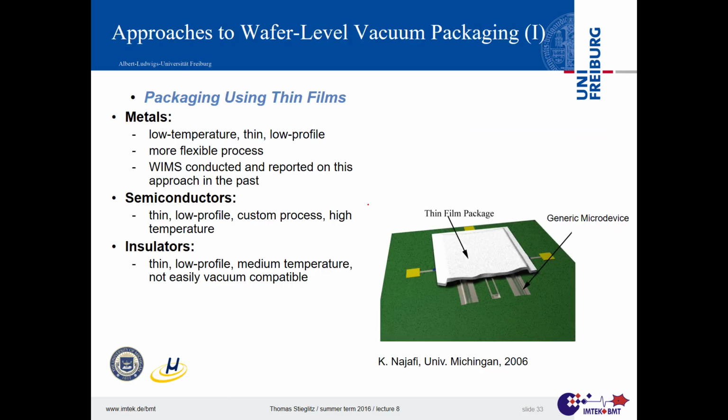And they started with thin films, so having your device with electronics, and this is a simple idea, taking an insulating material on top so that you have no short circuits, and then putting a metal layer on top like a titanium package, but made out of thin films. You have to take care, if your thin film has tiny little pinholes, water can go through. Polymers like to store that water, and then you have a beautiful water storage case under your thin film package.